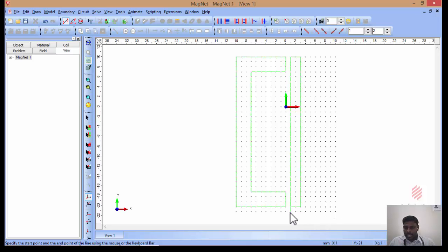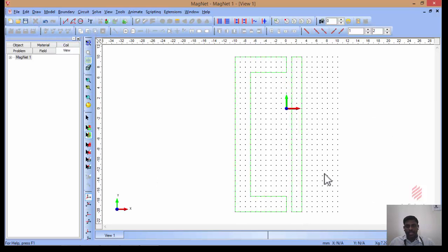So here we get an extra line. How do you cut this one? Go to select construction slice, highlight this one, choose the line, then go to segment edges. Once you segment edges, this line and the extra line will get separated. If you highlight this, automatically this line will remain different. So you can delete this line.